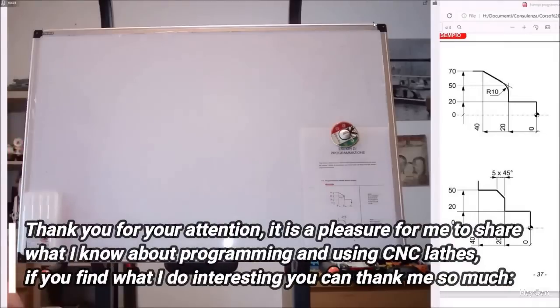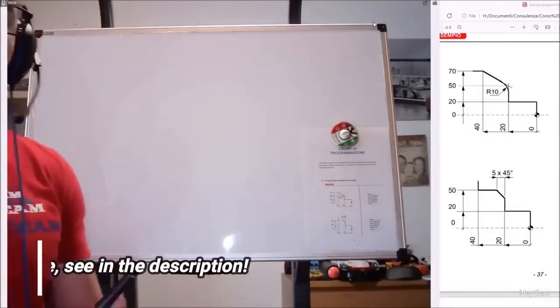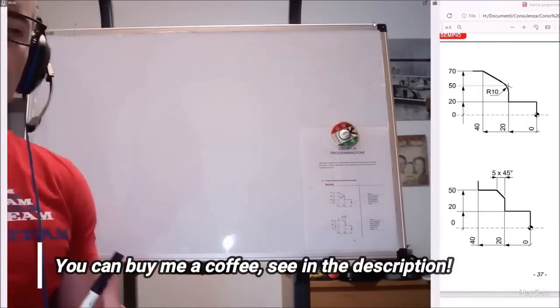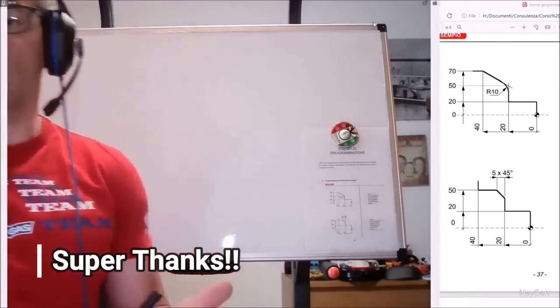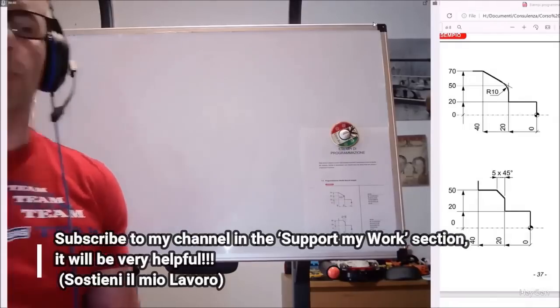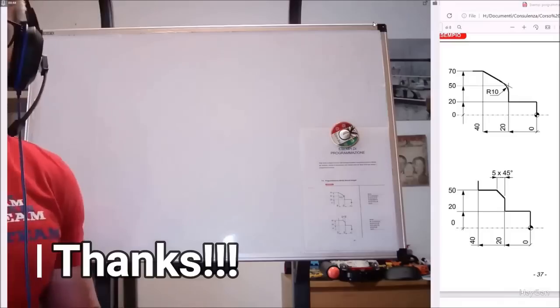In the last lesson, we saw that we can move in G0, G1, G2, and G3, thus in a linear manner, in rapid linear motion, in working linear motion, and in a circular manner. These are the interpolations: linear interpolation and circular interpolation.